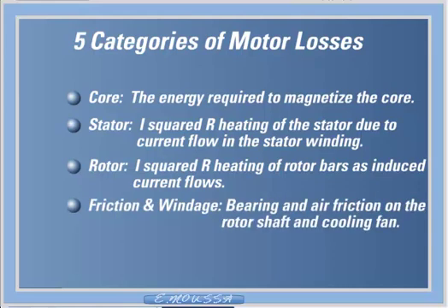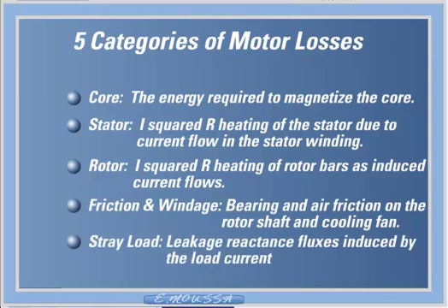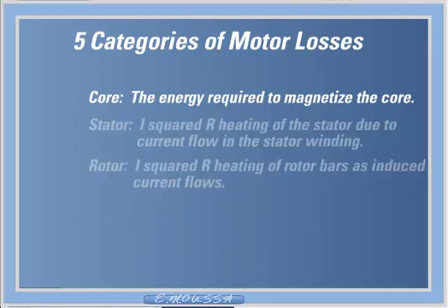Friction and windage losses due to bearing and air friction. Stray load losses. Stray load losses due primarily to leakage reactance fluxes induced by the load current. Core, stator, and rotor losses typically make up greater than 80% of the total motor losses.